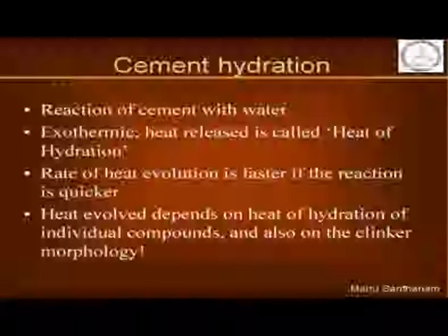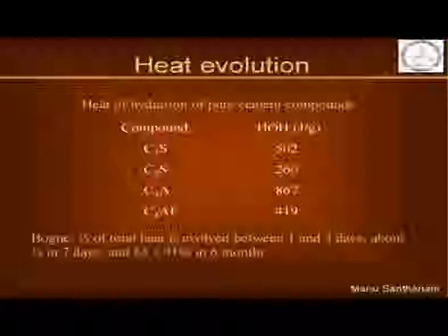So, now let us look a little bit further at this heat of hydration and how the different compounds rank in terms of heats of hydration. If you look at the heat evolution amongst the cementitious compounds, the highest heat evolution happens with the C3A.